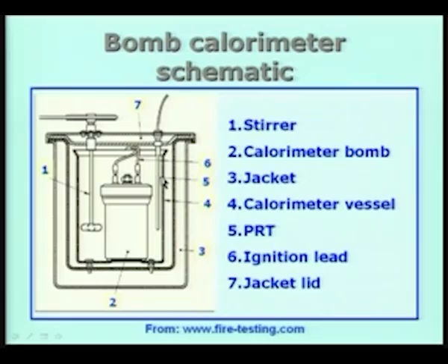It is well circulated, and there is a high precision thermometer which is immersed in that vessel, because that is a very important thing. The thermometer which is immersed in this water must be able to measure temperatures with a resolution of 0.01 or better. That means 0.01 degrees or better precision is required for the thermometer.